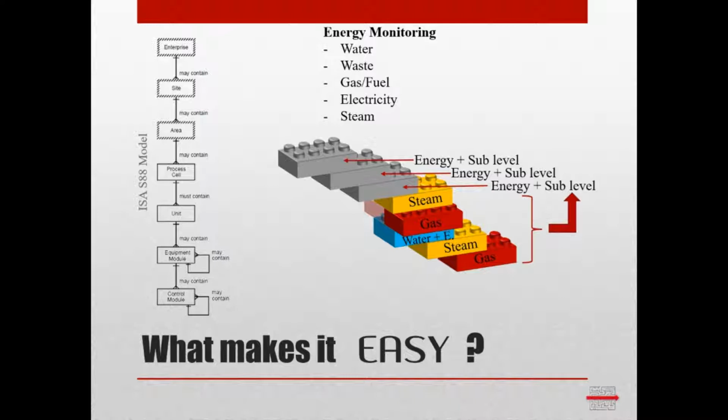Without programming, in the SCADA system, I can see the complete energy consumption of the plant, and by drilling down into the area, I can see the area consumption, the machine consumption, up to the individual component. The big advantage of this is that the energy values are in the same historian together with my process values and my operator actions, allowing me to make correlation between my energy consumption, my process and my operator actions by simply using Excel or Power BI.